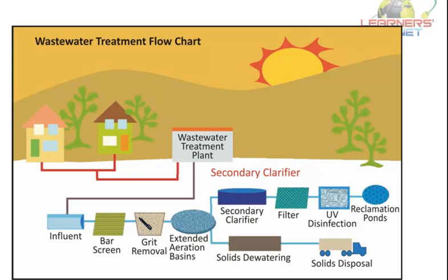quality. And so the related technology can be very expensive, requiring a high level of technical know-how and well-trained treatment plant operators, a steady energy supply, and chemicals and specific equipment which may not be very readily available. So an example of a typical tertiary treatment process is the modification of a conventional secondary treatment plant to remove additional phosphorus and nitrogen. So here you can see the wastewater treatment flow chart in which they have shown all the processes, including from the primary to tertiary process, right?